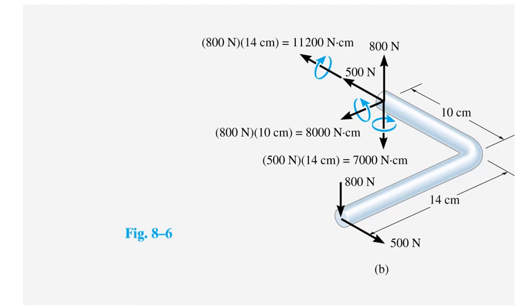So we have point A here to point B. If we take the free end here, you have to determine what the reaction forces and moments acting on this cross section are due to the applied loads. The applied load of 500 newtons has a radius arm of 14 centimeters. Using that radius arm, it will have a moment about z. So this is z here, vertical is z.